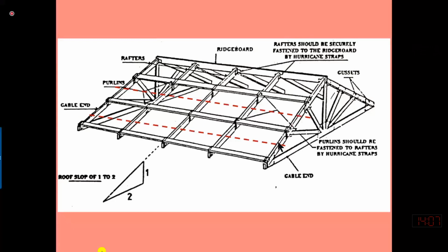Sometimes, to reduce the panel length, we can place the purlin on the top chord. If the purlins are placed directly on the top chord instead of at the panel point, then we need to design this top chord as a beam, because the end reaction transferred on the top chord will behave as a point load acting at the center of the beam.